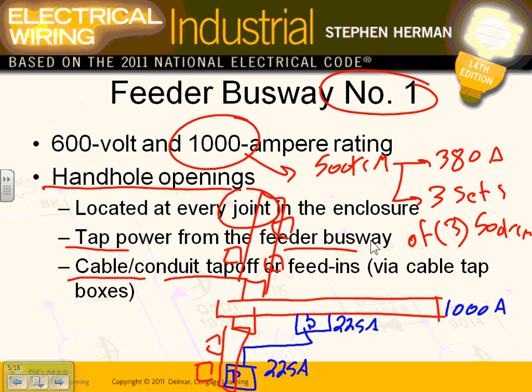If you look at the picture that we had, here's another, and let's just say this is a 400 amp fuse. So here's a 400 amp fuse right in here, feeding a plug-in busway, and also a 225 amp circuit breaker or fuse feeding a panel through conduit and wire. That's what they're doing in feeder number 1, tying to a panel or a circuit breaker. Any comments, guys?